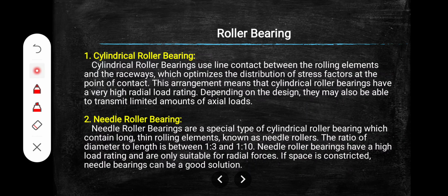Needle roller bearing is mainly started with K, HK. The most common names start with NUTR, NATR. These are some examples of needle roller bearing nomenclature, NATR, sometimes NUTR. This is the type nomenclature of needle roller bearing.